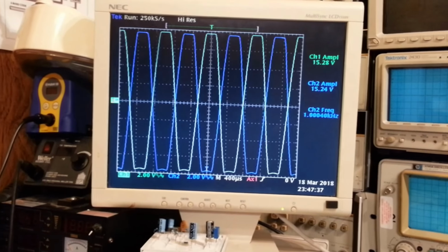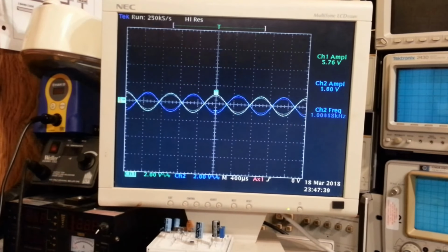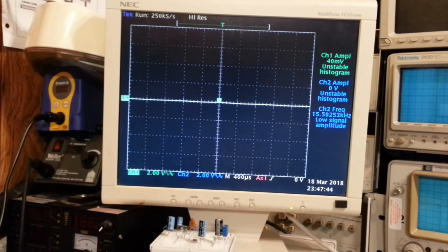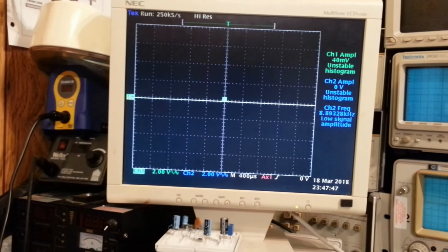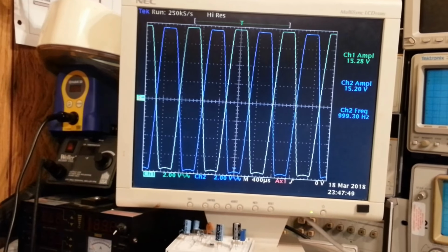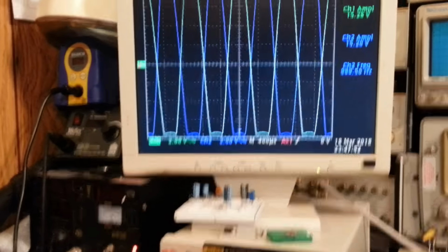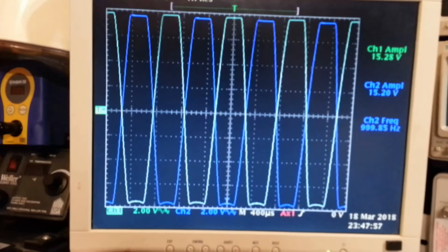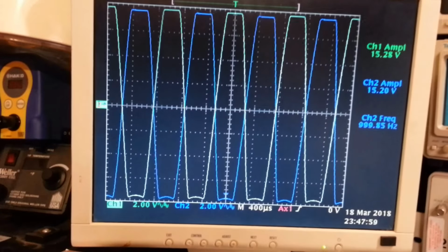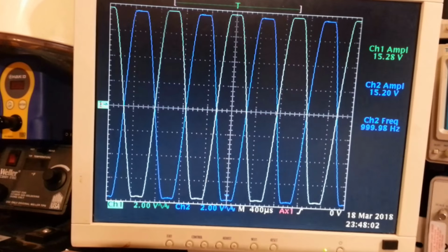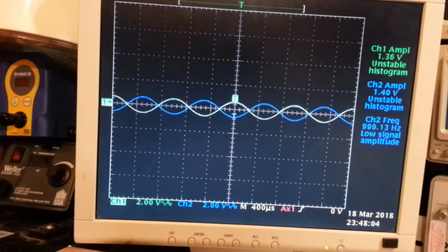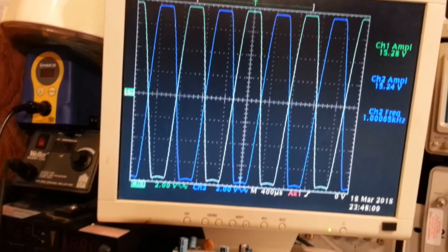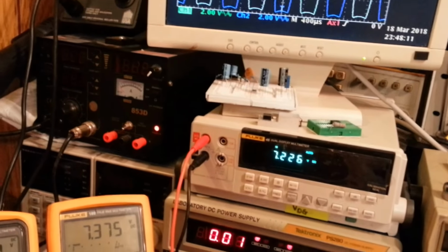You can see there's no noticeable DC offset on the waveform. It just nicely varies from minimum to maximum. There's no DC offset because the second stage differential amplifier is canceling the common mode input from the first stage, right? So we don't have to worry about that, because the second stage differential amplifier allows us to compensate for the quiescent point shift.